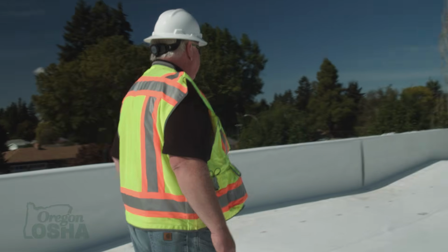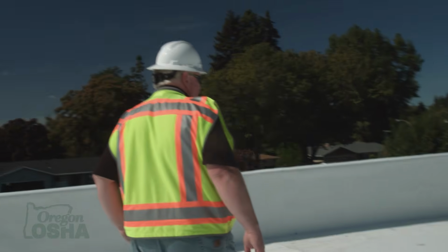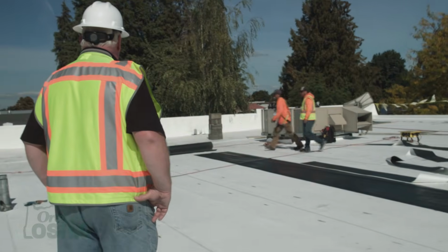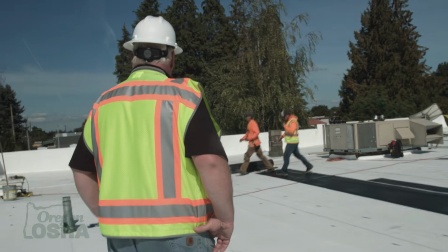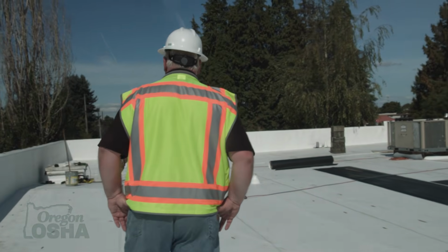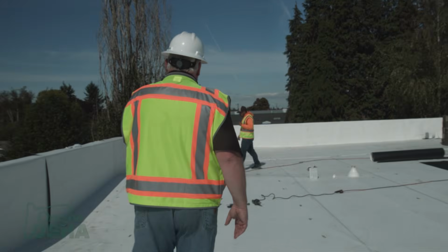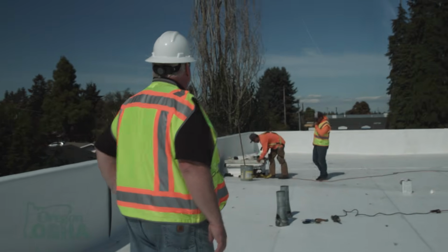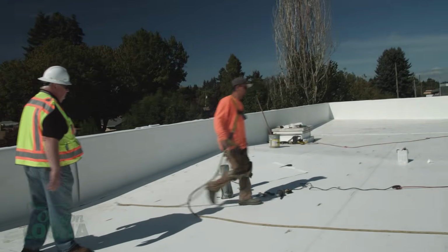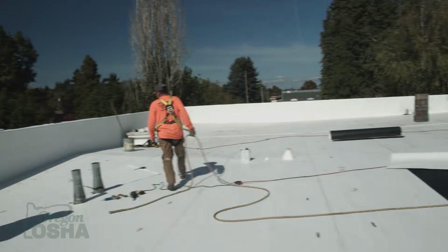The safety monitor system uses a competent person to warn roofers when they are in danger of falling. Since the safety monitor is responsible for recognizing fall hazards and warning workers about them, they are required to stay on the same working surface as the roofers and avoid doing any other work. The safety monitor system is available as a primary fall protection option for roofs that are 50 feet or less in width.